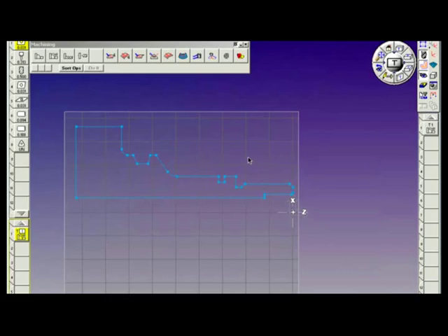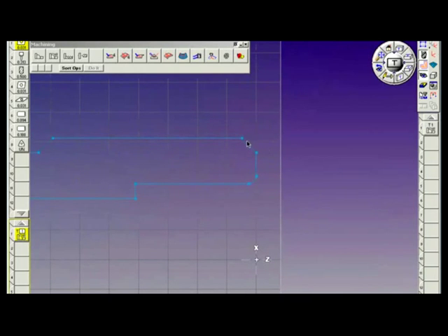All right, I'm going to zoom up right here, select the chamfer as my start feature, and you notice the markers appear with the cutter on the outside of the geometry and the cut direction pointing towards the chuck. My markers are all grouped at that same location.